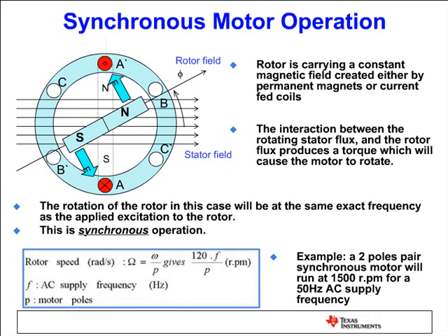The horizontal vectors are created by phase A. I'm going to talk about the three-phase operation as well, but here only one phase is excited. The horizontal field vectors interact with the magnet because the stator is sort of an electromagnet right now. The field of the magnet and the field of the stator interact, and that's how the motor spins.